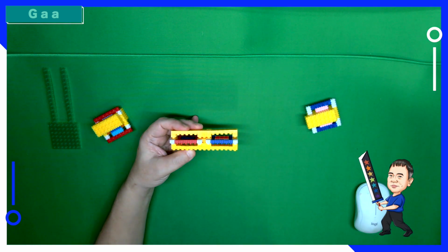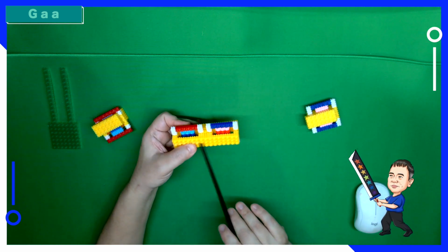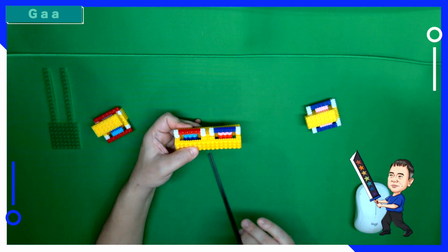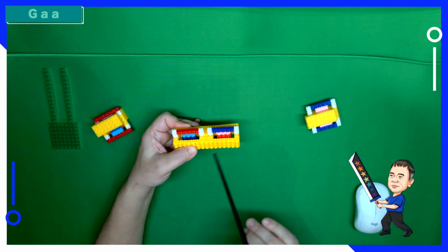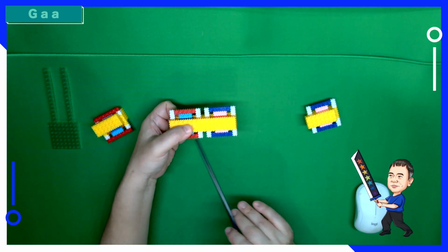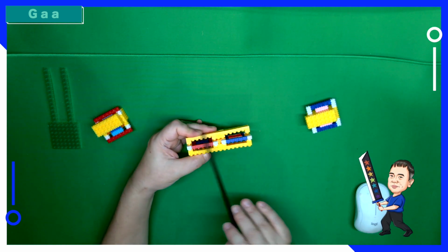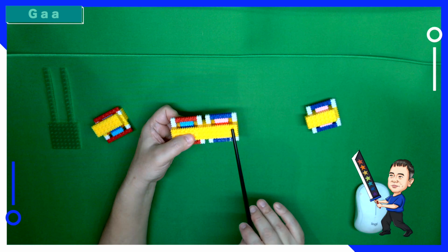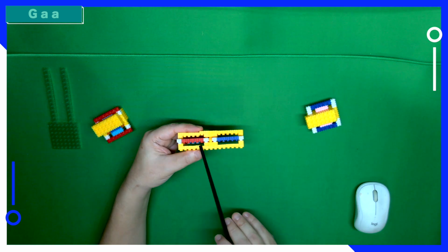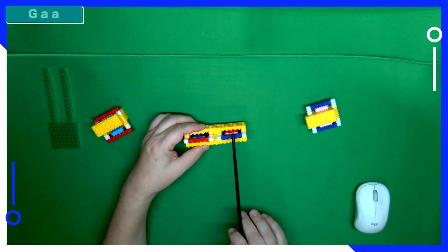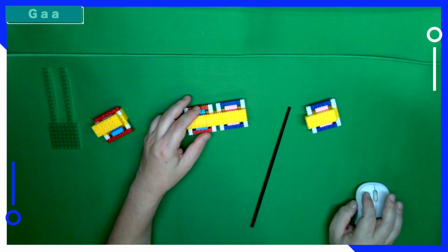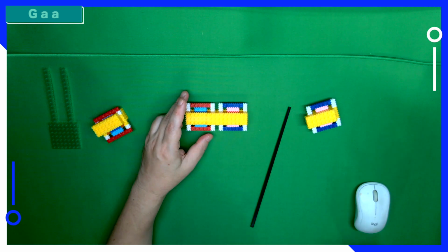Now, if we apply the positive voltage, then the N channel will open, P channel will close. If you apply the negative voltage, then the P channel will open, N channel will close. So only one channel will open at one time, one and only one channel. So this is what complementary stands for. I put them together, then they become complementary, and it's a gate all around for both N type and P type. So that's complementary gate all around.